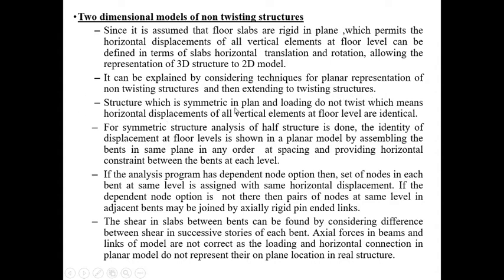When the structure is symmetrical in plan and loading and does not twist, that is, rotation is not allowed, it means that the horizontal displacement of the vertical elements will be the same at each floor level.